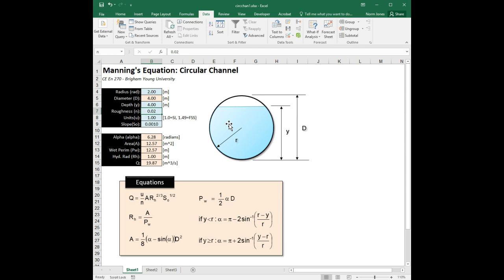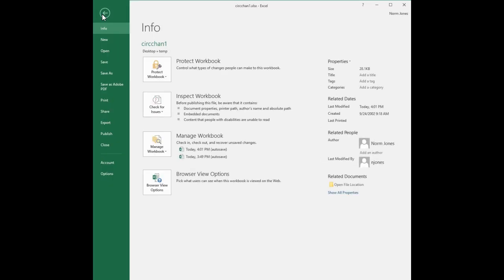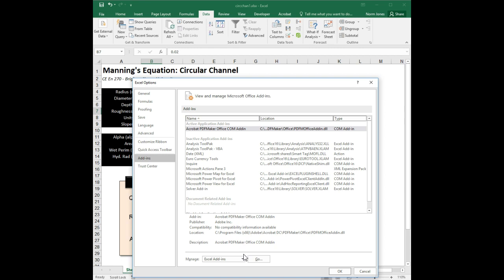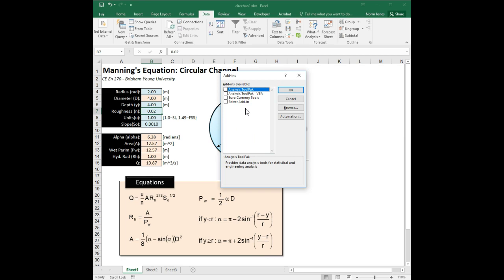So what we're going to use here is called the solver. And the solver is an add-in. Now there's something we need to do in order to get access to the solver, and that is, you need to go into the File menu and go down to Options and go to Add-ins, and down at the bottom we want to do Excel Add-ins and do Go, and then you want to turn on the solver add-in. By the way, each of these steps is listed in the chapter on GoalSeek and Solver in the Excel VBA primer.